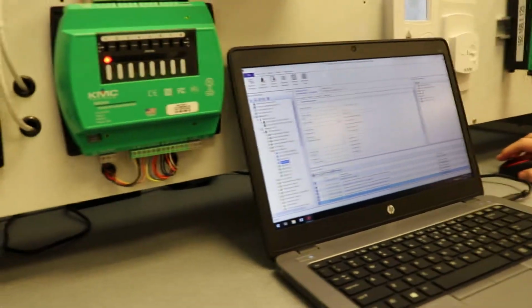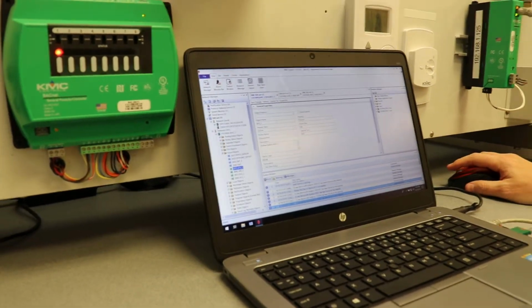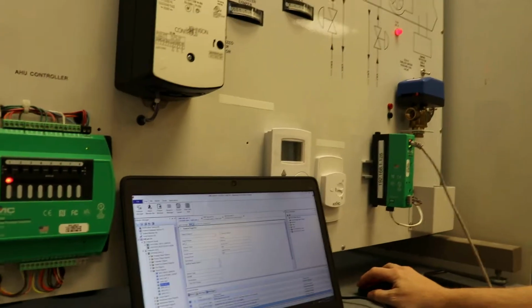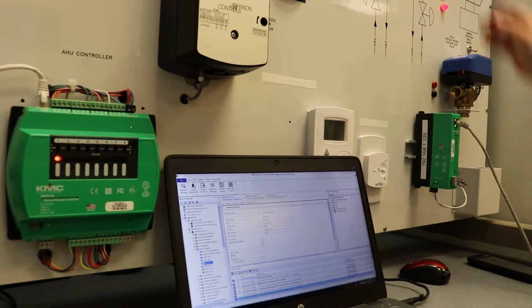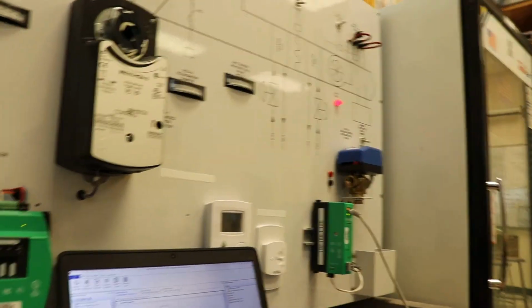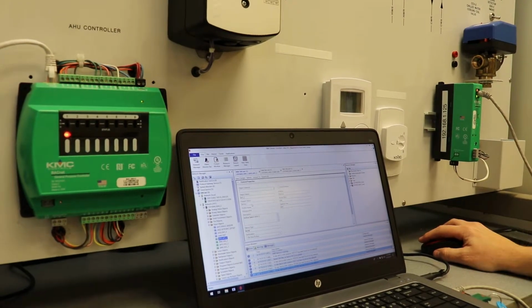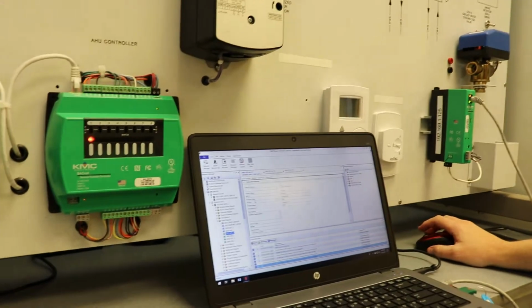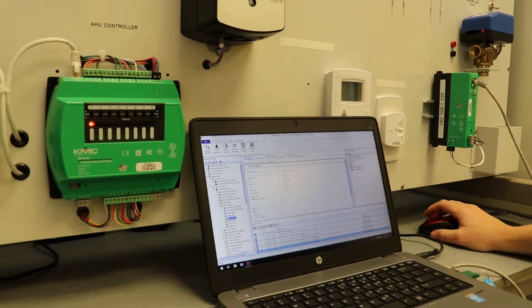Okay. So airflow switch. So right now it's active, telling you that okay, the airflow switch is on. Now it's inactive, so now the airflow switch is off. Okay. And that's always going to appear under the present value. So for every single one of your objects, it's going to have a present value property, and that's going to be what it's reading currently.